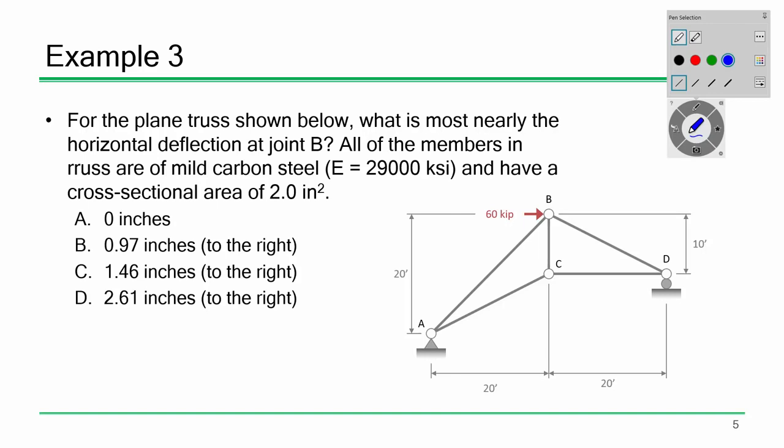So we'll review that. For beams, there are 3 ways to do deflections that I think are effective. Number 1 is double integration, which I'm probably not going to cover, but we can talk about it later or at another time if you're interested. You can do the unit load method, or you can do what we're going to do tonight, which is just use the manual, and it ends up being a lot quicker. But the unit load method definitely deserves a little bit of review, and that's what we are going to do tonight. Okay? So, let's go through the problem.